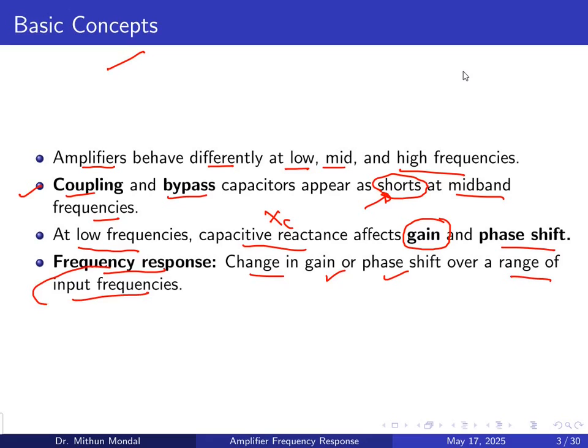The frequency that we provide as the input, this is basically a sweep frequency response. So we can give the input frequency of our choice depending upon the application, and this will affect the gain as well as the phase shifting. The measurement principle and the analysis is known as frequency response analysis.